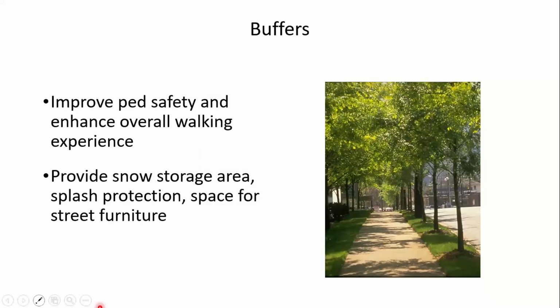I mentioned the buffer zones, that they do have a number of advantages. The place to put street furniture, separates the pedestrians from the vehicles, maybe splashing of water during rainy weather or in northern climates. That buffer zone can provide a place for snow storage, so the snow is not plowed right onto the sidewalk, and have a number of benefits.